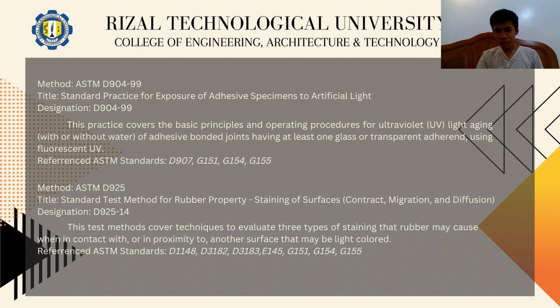The results obtained may vary when operating conditions are varied within the limits of a given method. Comparisons between materials must only be made when they are tested at the same time in the same instrument. Be sure to accurately report the operating conditions.